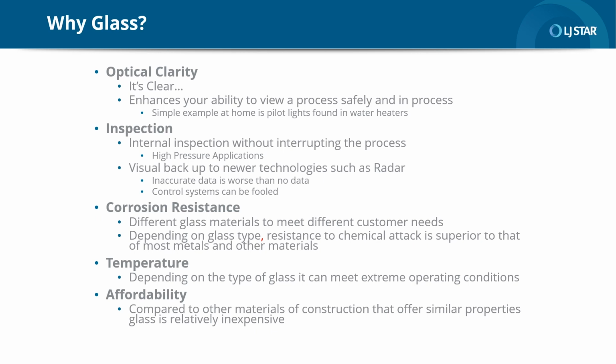There may be a sight glass that they can view inside to make sure that it's not getting towards the top of the tank. Because I have seen time and time again historically where companies have overfilled tanks because they've relied too heavily on some of these newer technologies. Some of those materials that they were loading are considered by the EPA to be dangerous.